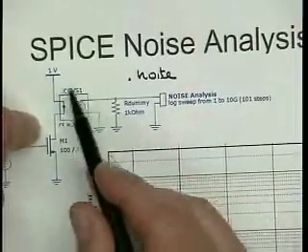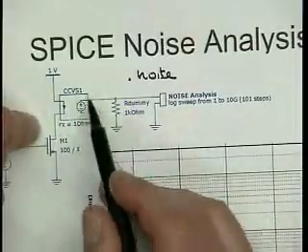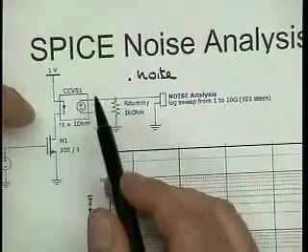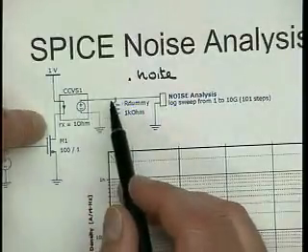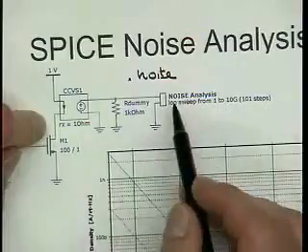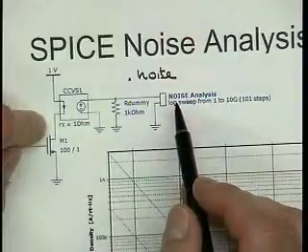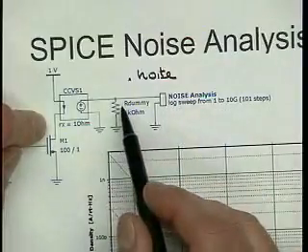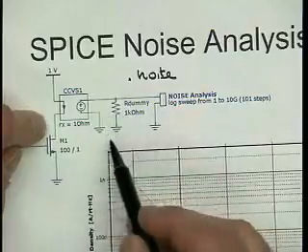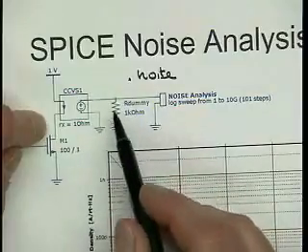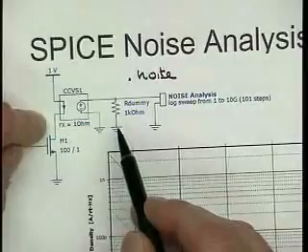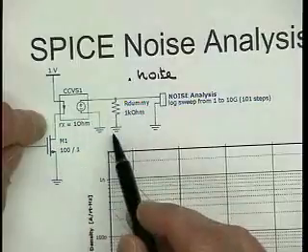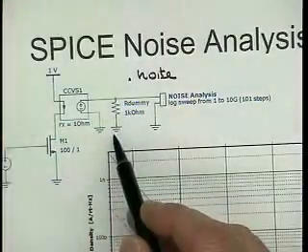Okay, so then we can use this transresistance amplifier, the ideal model in SPICE, to turn the current into a voltage and then use dot noise on that voltage. That's what I've done here. SPICE will complain if you don't also add other elements to this node, so I just added a dummy resistor. Of course, this resistor also has noise, but it doesn't matter in this case because it's driven by a voltage source, and consequently its noise source is shorted out.